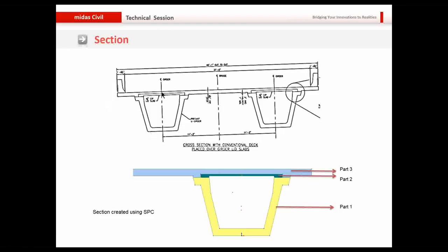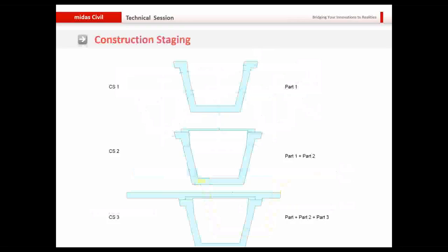And for the negative support section, it actually has a plate. For the non-support regions, it doesn't have a plate. We pour the concrete straight onto the false board, but this is how it's done for the support regions. And this is what I'm going to show shortly using the CAD and section property calculator tool in Civil.